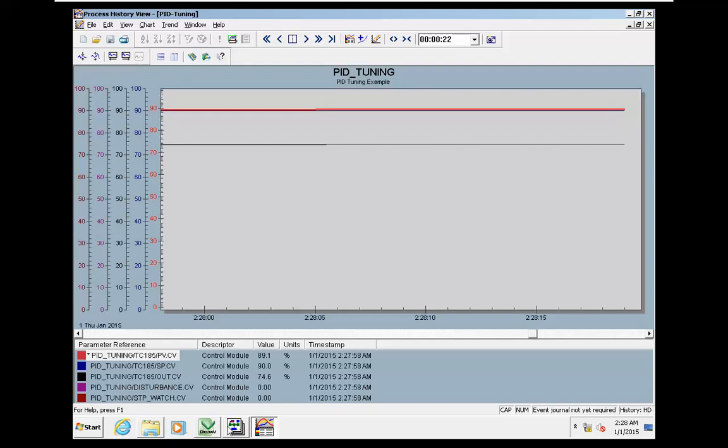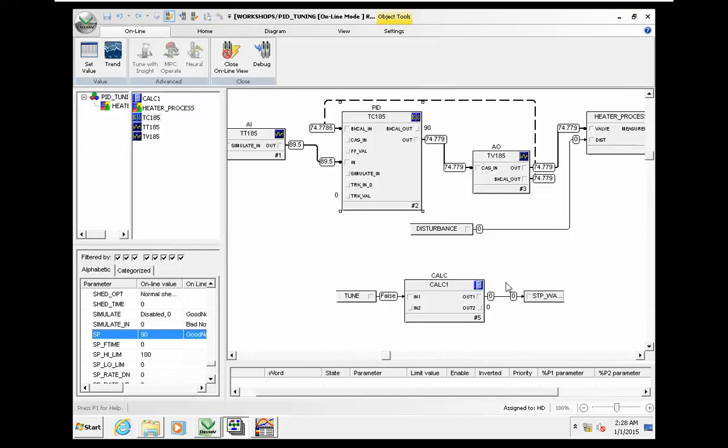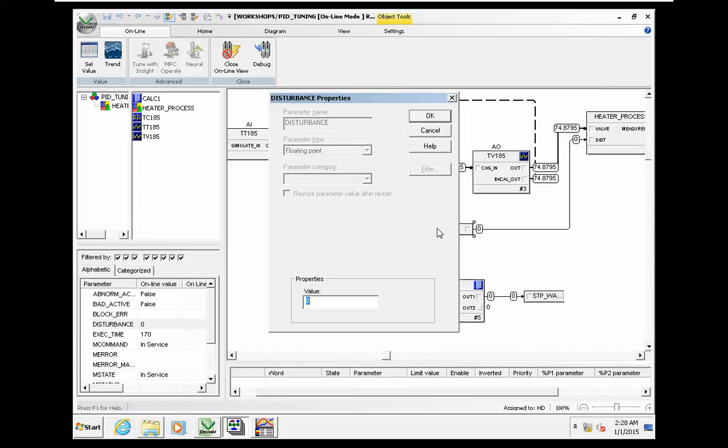Now it's possible for us to check the disturbance. In normal conditions, for a startup and for warm up, I suggest to use aggressive PID to go from 0 to a high set value. But for normal operation, conservative PID is okay. Conservative PID is okay for small step changes in set value and for controlling the disturbance.